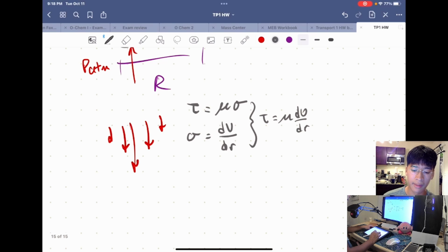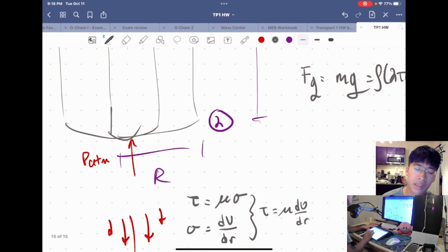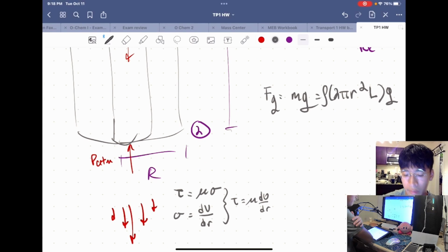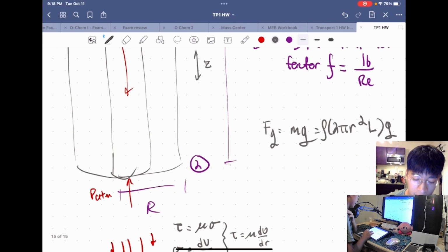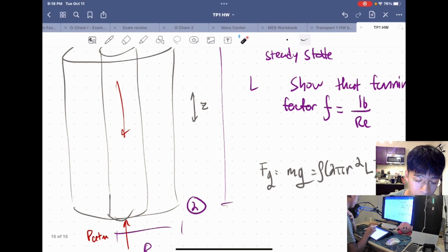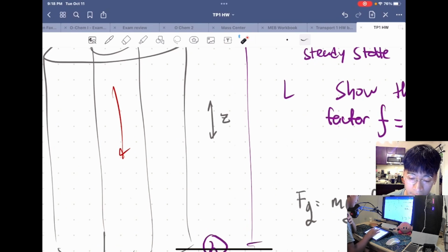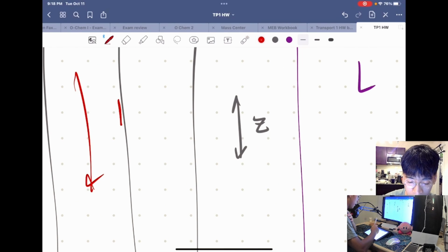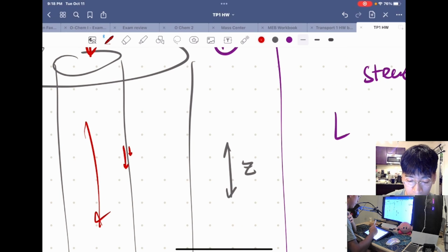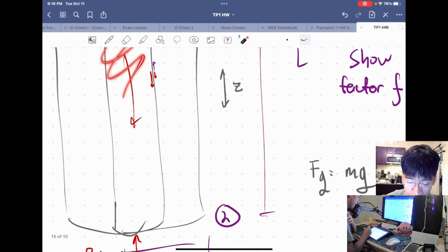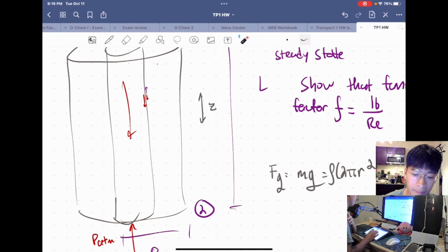So we have shear stress. Now, how about the force? I had hinted at the fact that the shear stress is in units of force per unit area. So the force is going to be generated by the area of the surface where the liquids are in contact with one another. So we're going to take a look at this liquid here, and the liquid directly neighboring it, right outside of our cylindrical subsection. And that's being dragged along, so there should be a force counteracting it, right? And that's happening all along the surface of the cylindrical section that we've defined.